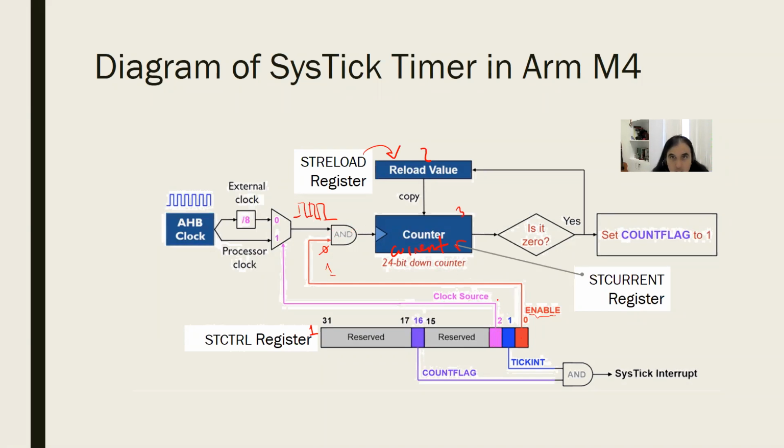This bit 2 is connected, this pink one. It was called the clock source. Do you remember? Does anybody remember what this shape is? Something simple. This is something that selects either of these inputs according to the value of this control input. So if this control input is 0, it gets this input and allows it as the output. If this is 1, it ignores this one, it gets this one and allows this as the output.